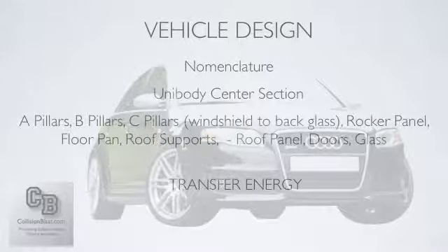Now we've got the center section, and this is your A pillar or windshield pillar, your B and C pillars. And basically, like I said, it's from the windshield to back glass. That is your passenger compartment. It also consists of the rocker panels, that's below the doors, the floor pan and the roof supports, and then you've got your roof panel, your doors, and your glass. That is basically all of your center section. And this part is designed to be really strong. You don't want it to absorb energy. You want the passenger compartment to transfer all of that energy, all that damage, around the passengers.